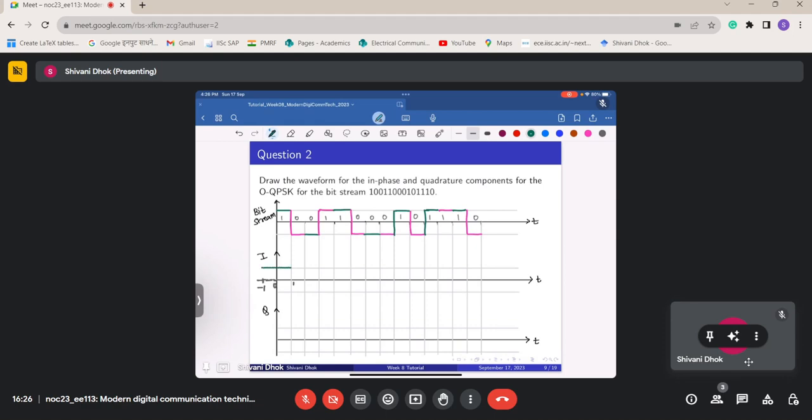In other words, the first one will use only one time slot instead of consuming 2. This is equivalent to adding an offset of +1, that is, we are shifting the QPSK in-phase components to the left by 1 unit. That's how we add an offset. So this is the first in-phase component, which was this 1.